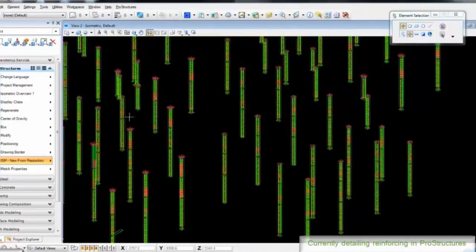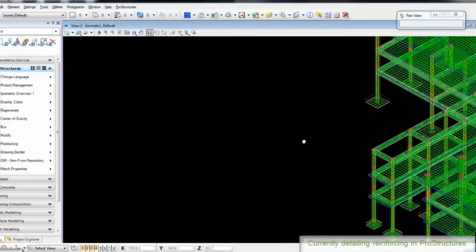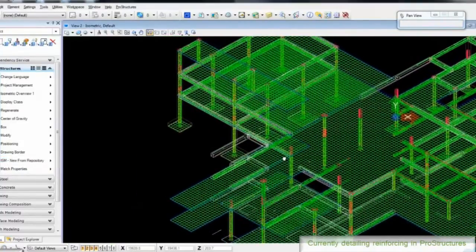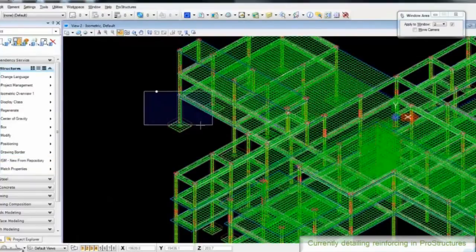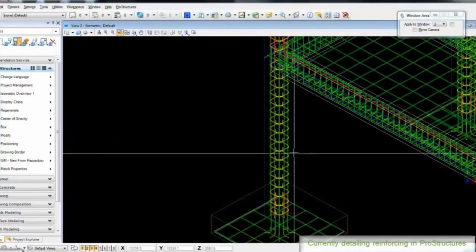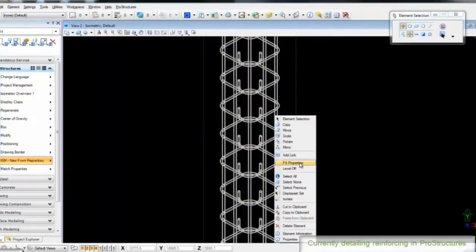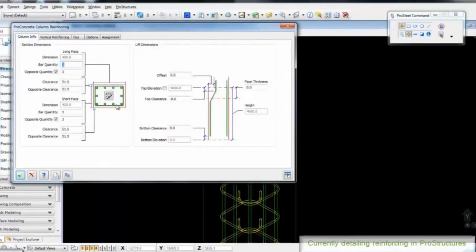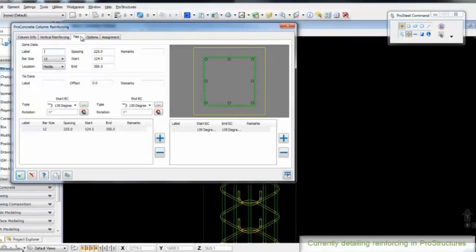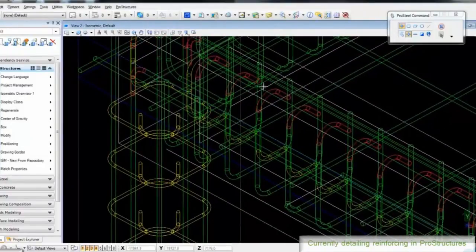The difference now is that we can actually edit this rebar. Okay, the ISM model was view only, read only. But here we can actually change the reinforcing. So what RAM did was it designed the reinforcing to fulfill structural code requirements. Okay, and it only took it so far. It provided a bar size, bar conditions that it felt suited as meeting code requirement. Here we can actually detail it to the level that is needed for the final placement of the reinforcing.